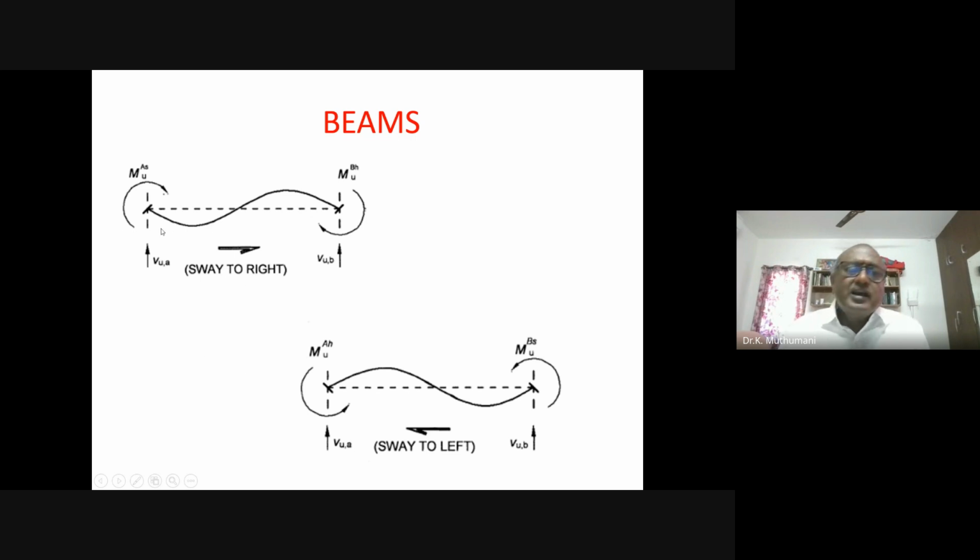Please understand that this is a very important point. Assume that the plastic hinge has formed here. That means for whatever steel that you have provided, suppose you have Mu as a number. What you do is compute Mu by fck bd square, find out the percentage of steel and go ahead. Now, because you have done that, you already have the steel available in the hogging area and the sagging area. For example, let me say 10 numbers of 20 mm at the top, 5 numbers of 20 mm at the bottom. That is for hogging, this is for sagging.